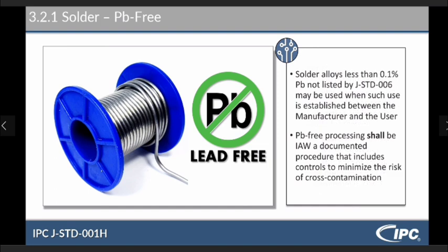So, lead-free solder. Solder alloys less than 0.1% lead, not listed by J Standard 006, may be used when the use is established between the manufacturer and user. Lead-free processing shall be in accordance with the documented procedure that includes controls to minimize the risk of cross-contamination.